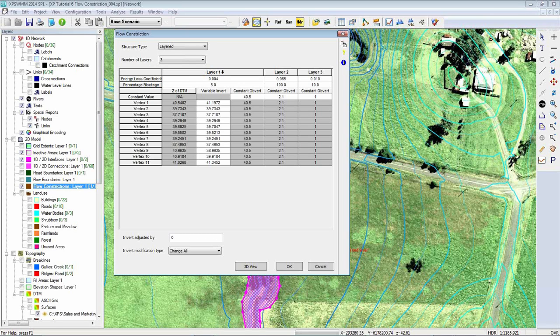So it's important with the energy loss that we are conscious of whether we're using that polyline or polygon, with the polygon being a loss per meter, as discussed by Bill, so that if you change your cell size you don't have to change the losses associated with it. So in this example these losses are losses per meter, which is why they may appear a little different to what you would expect.